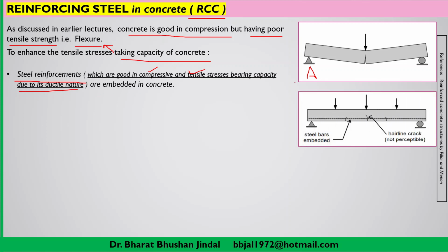In this figure you are able to see, in the first figure only a concrete member was there, and here what we have done is just embedded a steel bar. Now when load is coming on the beam, you will see only some hairline cracks. And when load is further increased, its behavior will change.